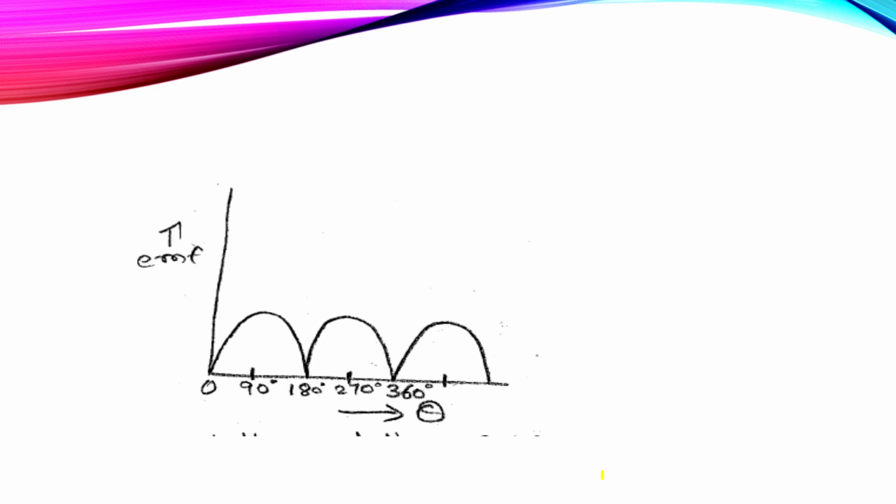To make the flow of current unidirectional, these slip rings are replaced by split rings. The split ring, made of conducting material, is cut into two halves or segments insulated from each other by a sheet of mica.